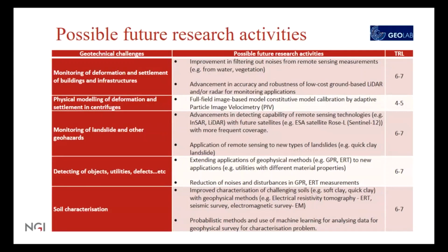Sure. Yeah, you know, for example, in Norway, NGI has a very nice large database of triaxial tests, and we've compared the data from their triaxial tests and their oedometer tests to shear wave velocity measurements, and there is a very nice correlation between the two sets of data. So I think there is great promise in that. Thank you. So you can use correlations that you have, but do you need to know the type of the material, let's say? You do. Unfortunately, those correlations are local. So for example, the same correlation that we developed for marine clays in Oslo doesn't apply to the marine clays in Gothenburg, even though they have a similar geological background. So you need to be careful. The correlations are very powerful, but you need to develop them locally.